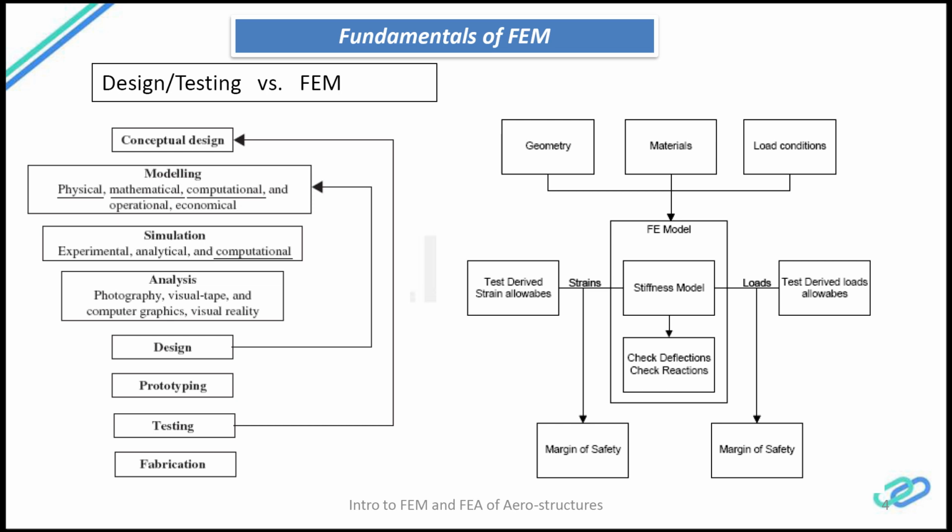Displacements, which are related to the strains, and loads, which are forces and internal reactions, for example if you want the free body loads, etc. Most aerospace industries use the finite element model and at the same time test the actual product, and then they correlate the results from the finite element model against the test results, just to prove the validity of the model and the product basically.